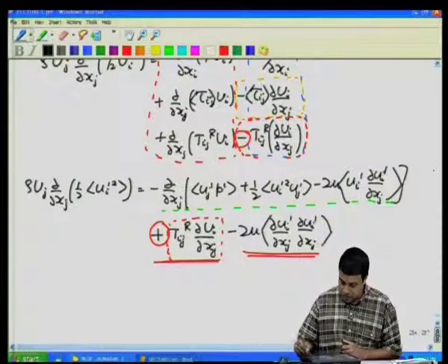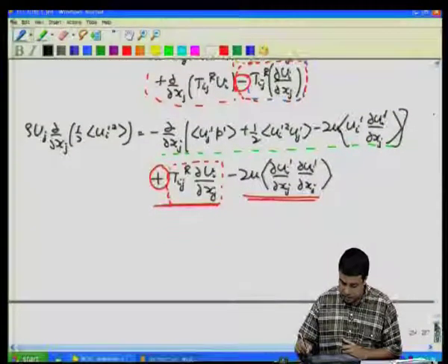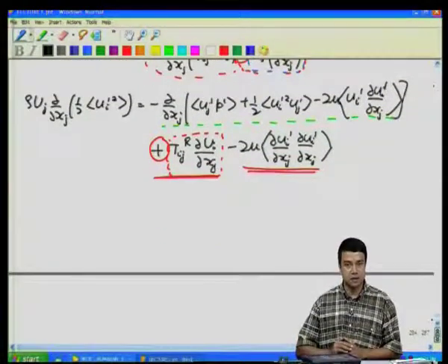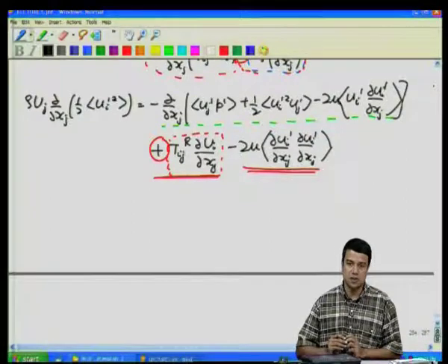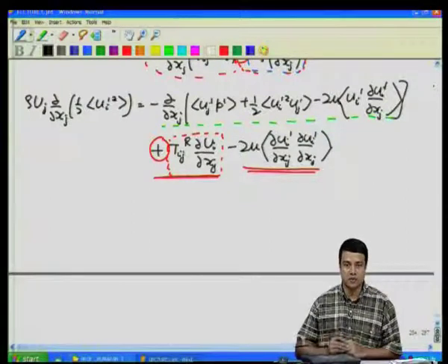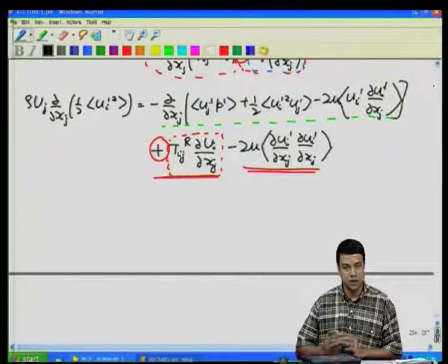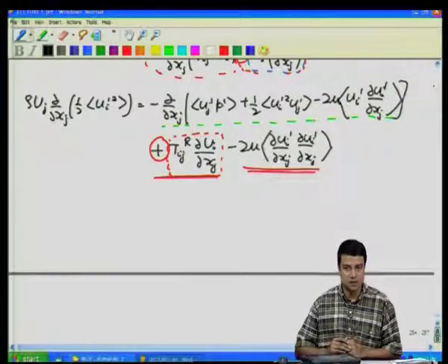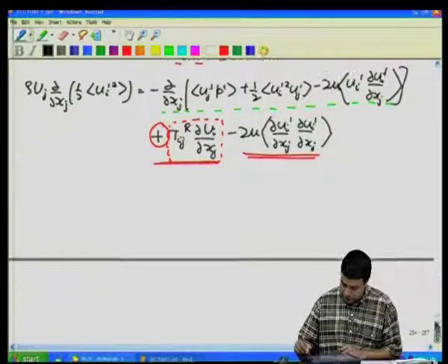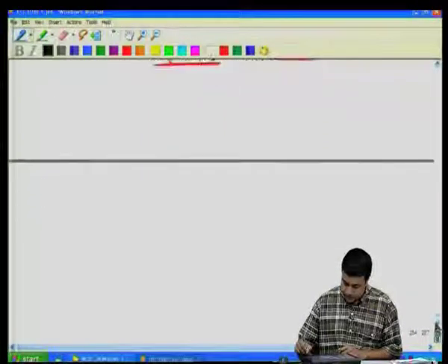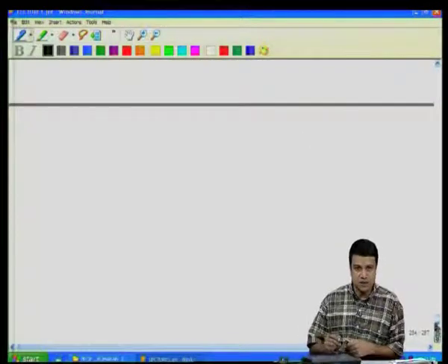So, next we looked at the question of where does the energy go. You have fluctuations of various length scales, starting from the largest ones which are comparable to the system size, the channel width or the boundary layer thickness, for example. Then you have smaller and smaller eddies of various dimensions down to the smallest scales. So, what are the smallest scales of turbulence?